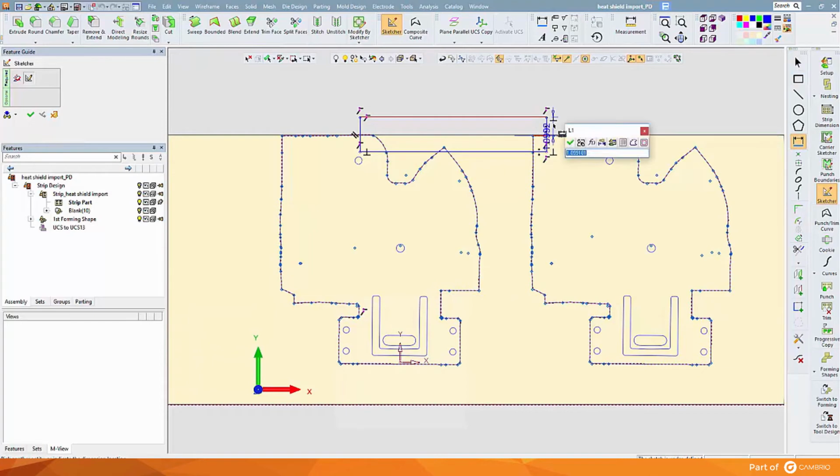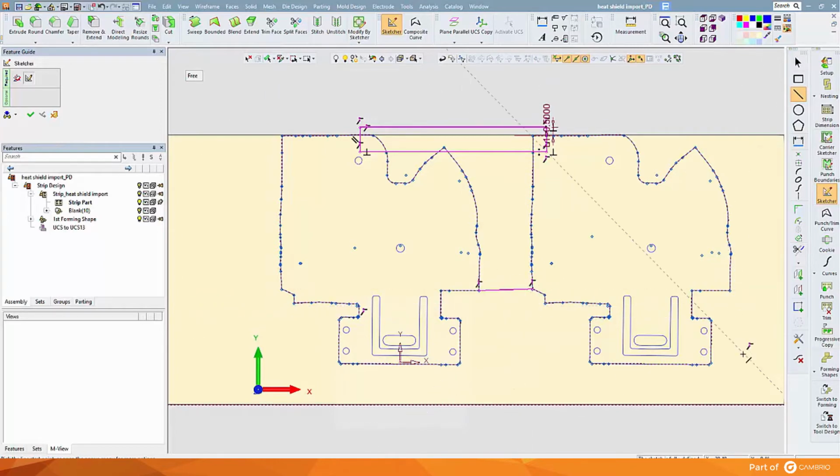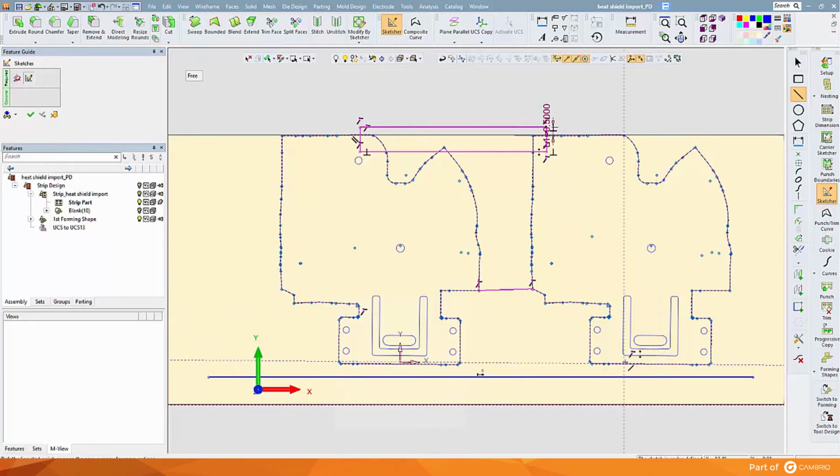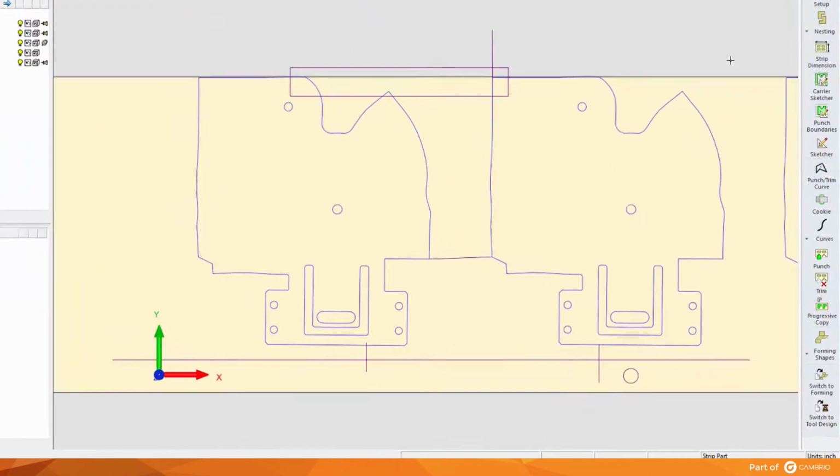So first we reference the blanks, and then from there, drawing up a rectangle to represent where a punch may extend out past the edge of the strip. Also, we will simply use a line to show where two punches would theoretically meet, even though in actual fact we'll design an overlap, plus some simple dimensions to control the sketch in general. We have now drawn in the carrier, and next the pilot. Throughout this, I am deliberately not trimming up the sketch, but using a rough sketch to show the power of Cimatron's strip design in creating punches.